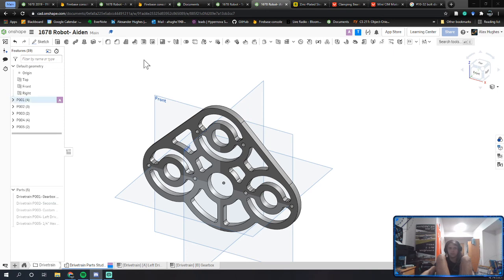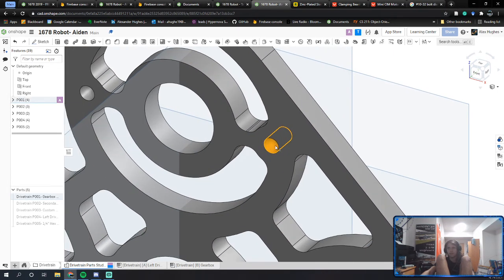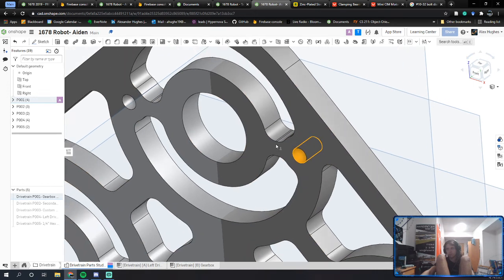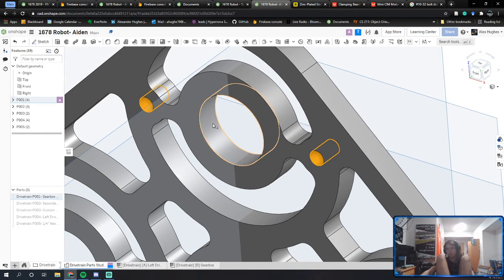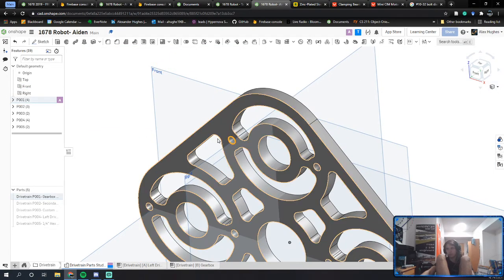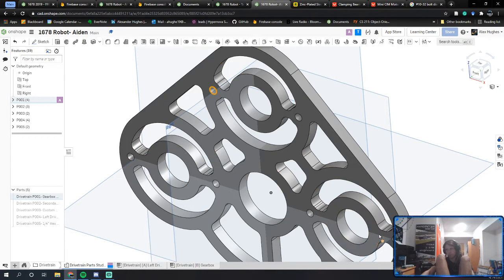Wait, what is changing to 3/16? I'm sorry, I'm just going crazy. You're changing these holes right here. Are you looking at my screen? Yeah. So these holes you want to change to 3/16. Anywhere those 10-32 bolts go through. So you have 6 holes on this plate that you need to change to 3/16.